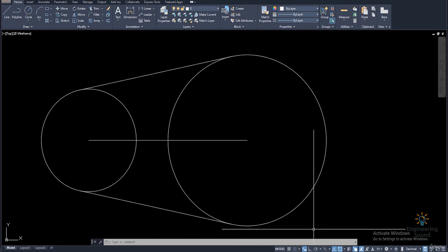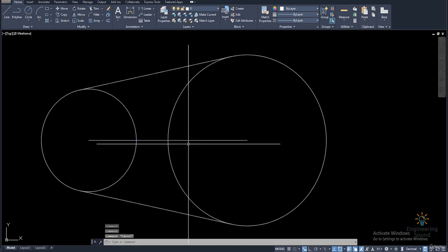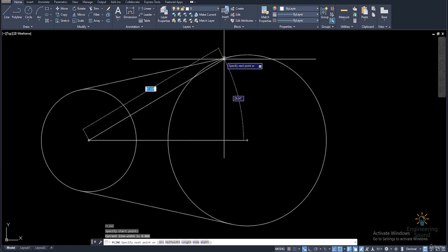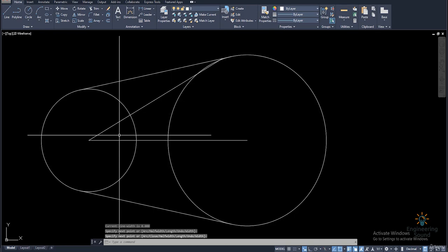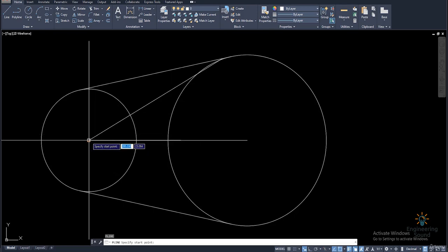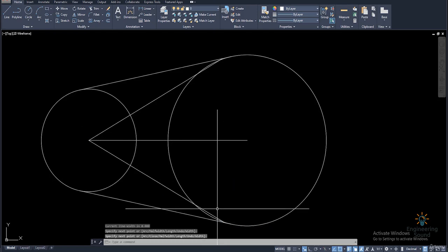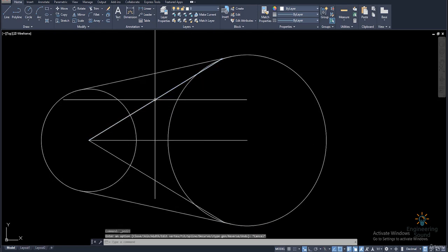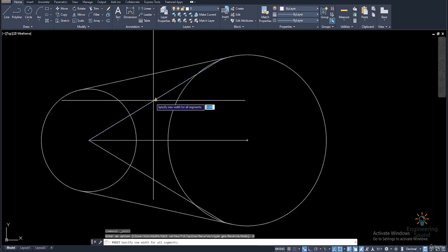If you turn it on and increase the width, selecting a polyline from here, I am going to draw a polyline from here to here. PL again here, from here to here, this option. Okay, providing the width, double click, or you can just select, double click, width, and I'm providing one.